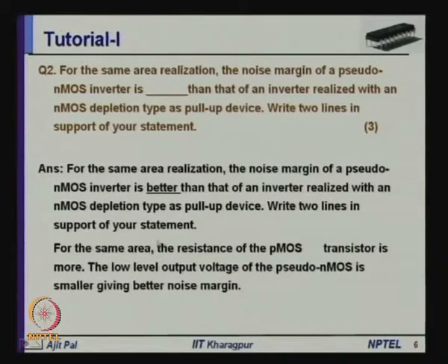and the statement in support of this statement you have to write, for the same area the resistance of PMOS transistor is more. As you know, PMOS transistor because of lesser mobility of holes with respect to electrons, for the same area a PMOS transistor will offer more resistance.